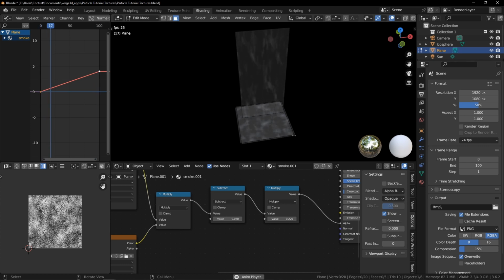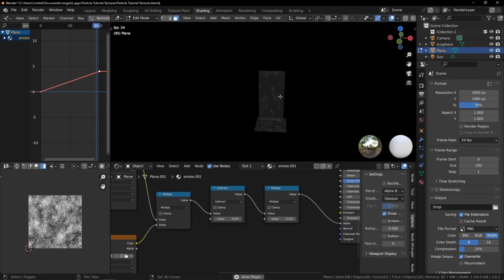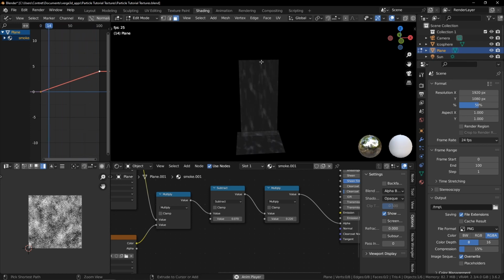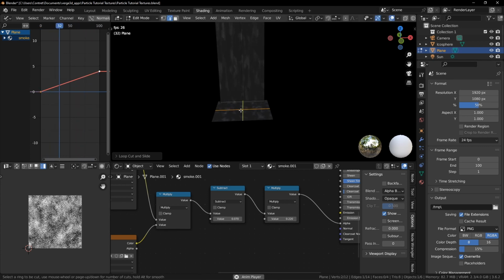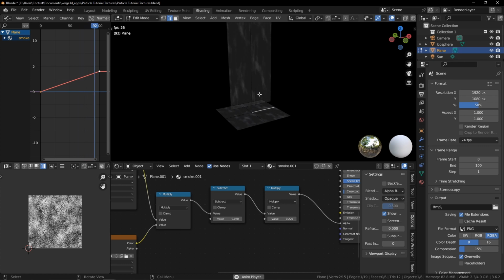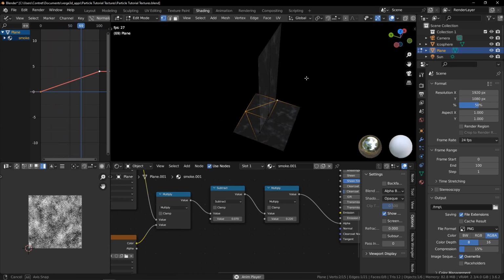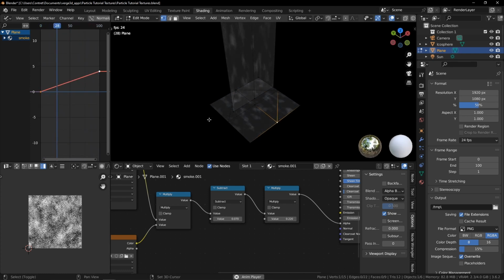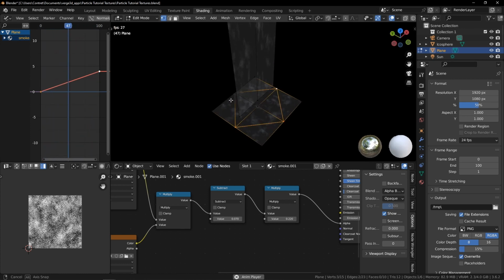What we need to do is to delete everything except two planes, the vertical and the horizontal one. Do not worry, we will copy them again later. Then let's add another edge right in the center of the plane, and two cuts for the horizontal plane. Then let's create this kind of rhombus object and subdivide the edges that we just created.